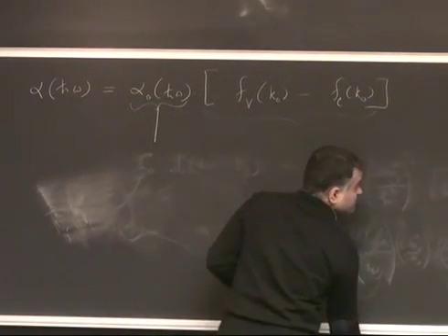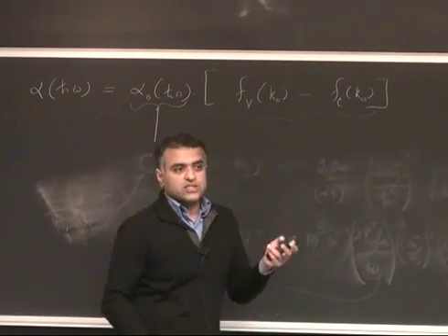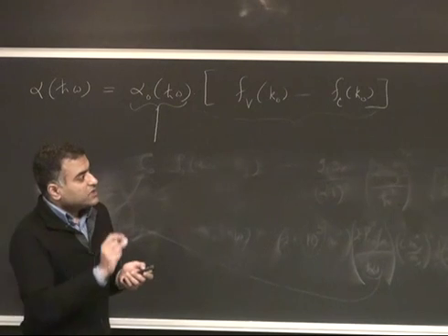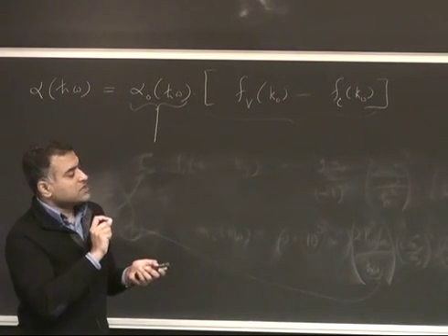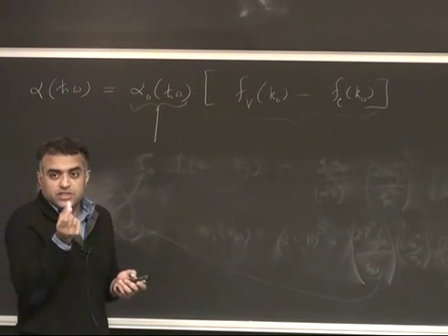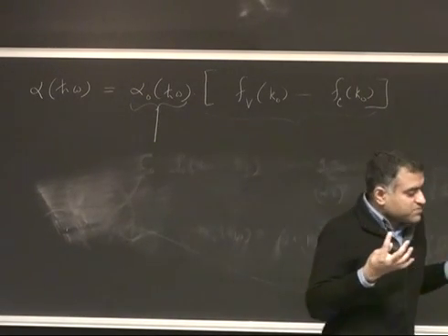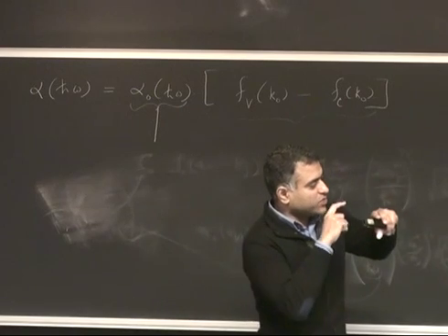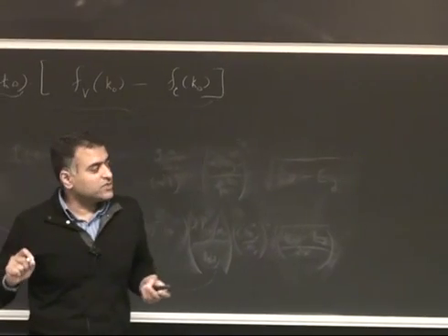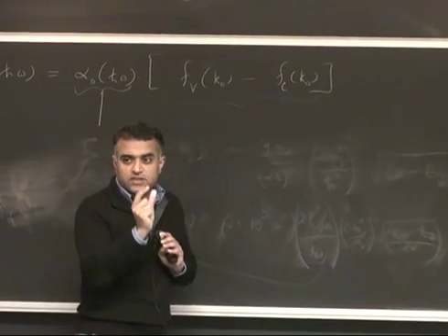And I think you can also see from just one more point here that as you increase the photon energy much larger than the band gap, it absorbs more and more, right? If you're just slightly above the band gap and your absorption coefficient is 10 to the 5, and if you are, I don't know, 4 times the band gap, it's twice. So it gets absorbed in an even thinner region. For example, take a 2 electron volt band gap semiconductor and shine 2.2 eV photons, then it may get absorbed in 100 nanometers. But if you shine 4 eV photons, it will get absorbed in maybe 50 or 30 nanometers. So it gets thinner. Makes sense?